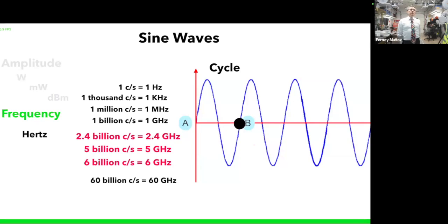In this class, we mostly will be talking about these three. Although, as I told you earlier, I am working with Wi-Fi HaLow. That's 802.11ah right now. And I have a HaLow link over there. We'll be doing some testing in the salt flats. This is a different technology that works in the sub-1 gig spectrum: 900 megahertz here in the US, 868 in Europe, and I don't know what frequencies other countries are using, but it's sub-1 gig.